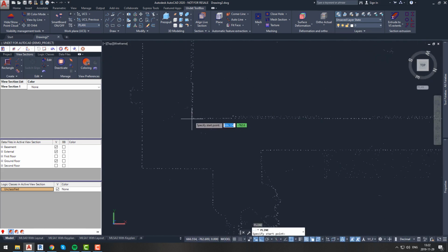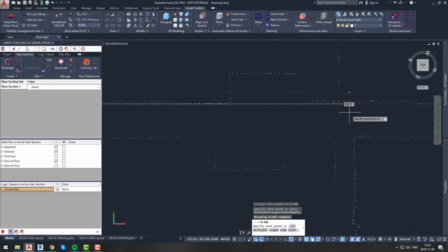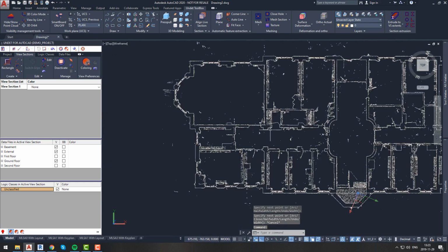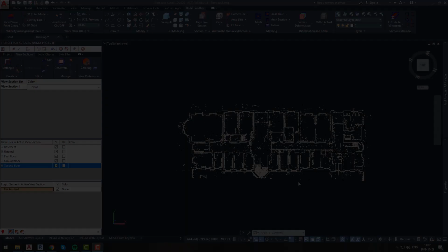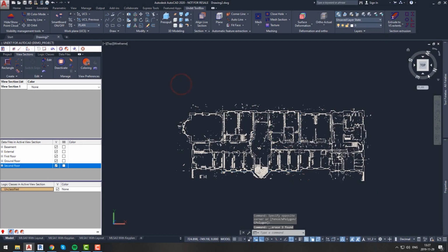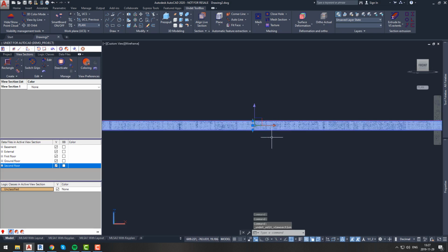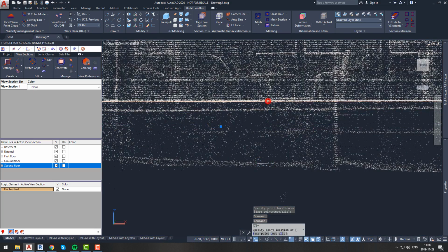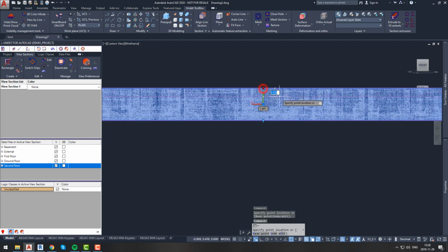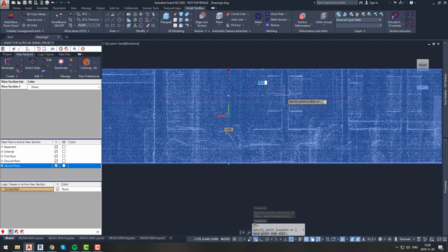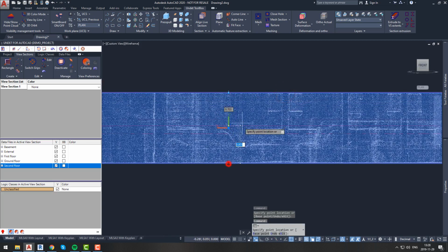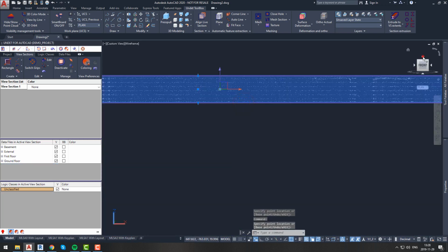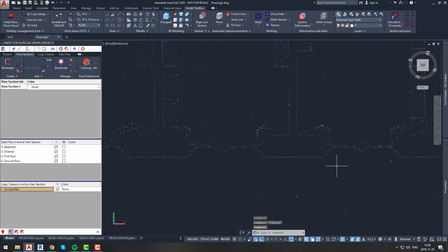Before we start that, we should know what kind of tolerance we will be using. Our practice shows that it is best to keep 30 mm tolerance while drawing perpendicular objects. So let's follow that. To draw external and internal walls we recommend to create about 20 cm thickness view section and lift it about 150 cm from floor level. This will allow you to see really good outline of walls, and you will be able to draw correct internal and external walls.